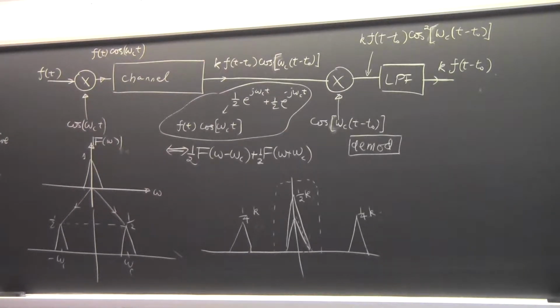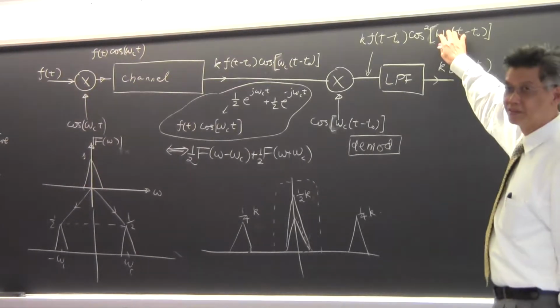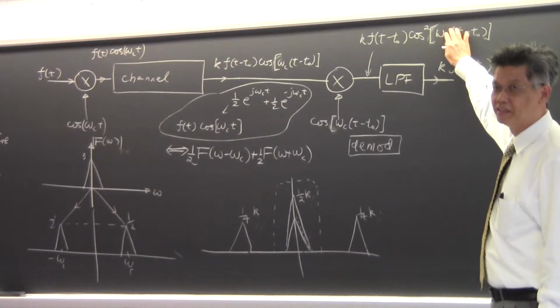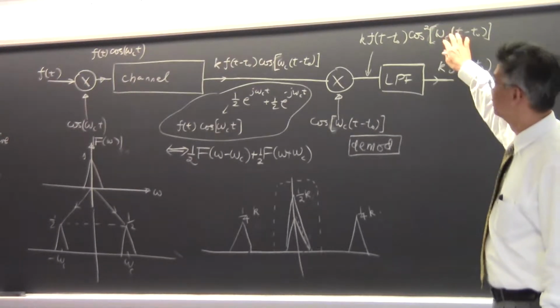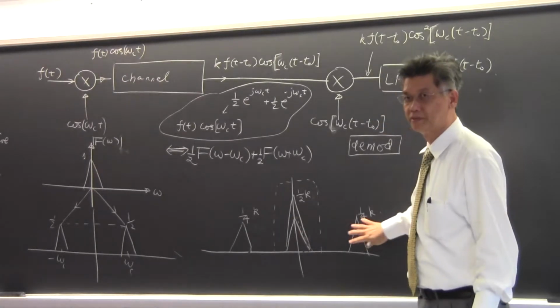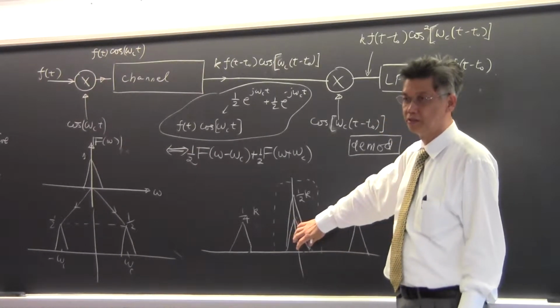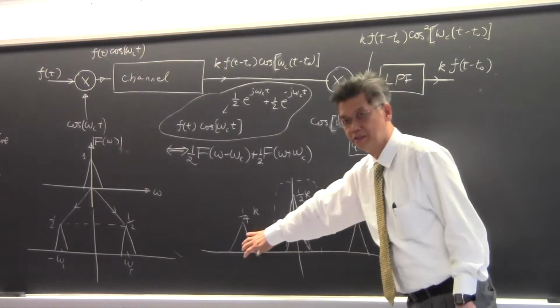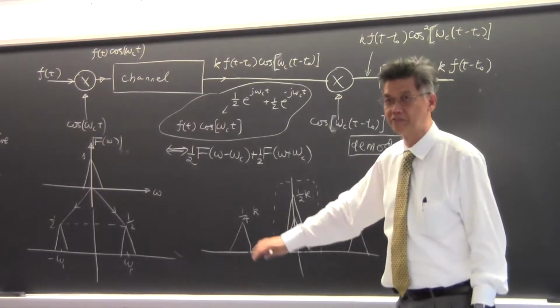So when you multiply by cosine the second time, it shifts each of those two peaks from the first one individually, and then stuff ends up back in the center? Right. You can pictorially think of it that way, rather than go through the math. You can also go through the math, expand this in terms of trigonometric identities, and then figure out what each term does. There will be 4 terms here. And that is what happens to the 4 terms. Two of them superimpose on top of each other. Two of them were shifted to the right and the left.